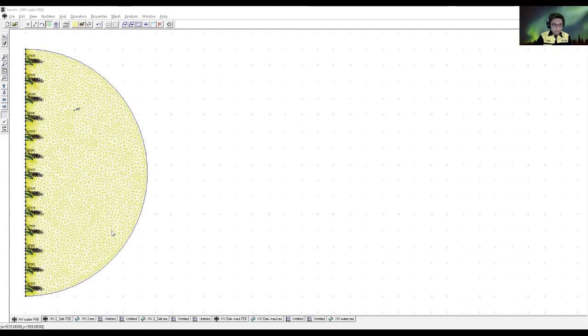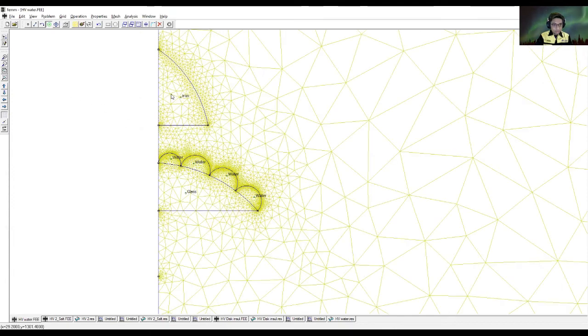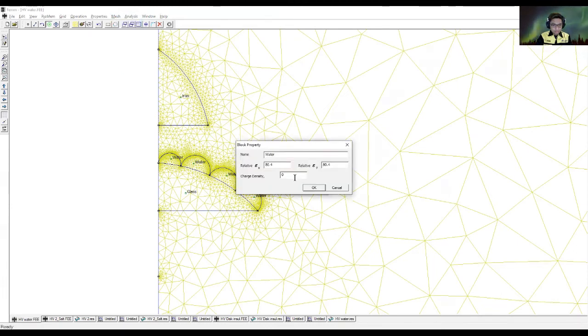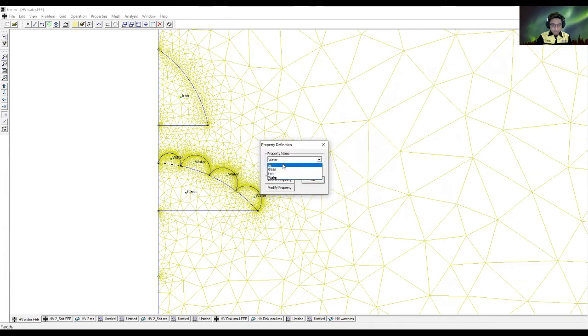As you can see here, we have included the water parameter: iron, water, and glass. We have also declared the permittivity coefficient for the water, which is 80.4. So we run the simulation and we can get the required voltage and energy graph.